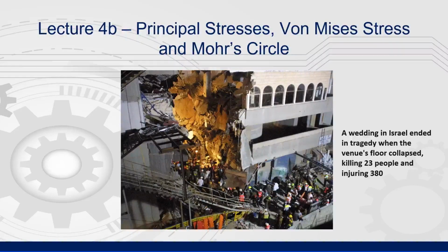The engineers involved in the construction of the hall were found guilty, along with the owners of the hall, of causing death by negligence, with prison sentences given to several of them. The initial design issue was identified as lightweight coffered concrete floor systems. It was discovered that the third story was under-designed for the actual live loading.